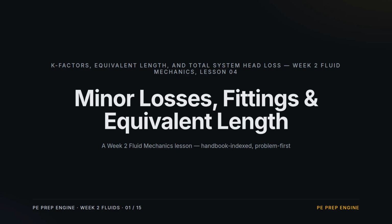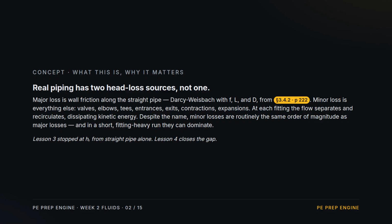Week 2, Lesson 4: Minor Losses, Fittings, and Equivalent Length. We build on Lesson 3's Darcy-Weisbach setup and add the K factor that turns straight pipe friction into total system head loss. Real piping has two head loss sources.